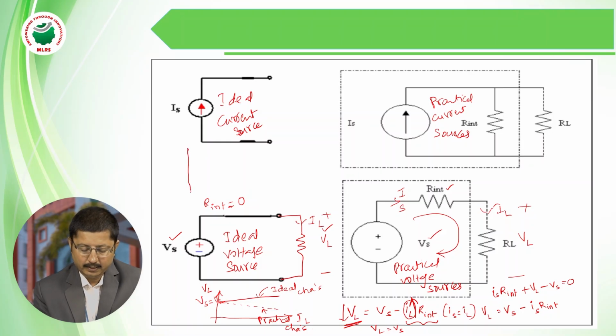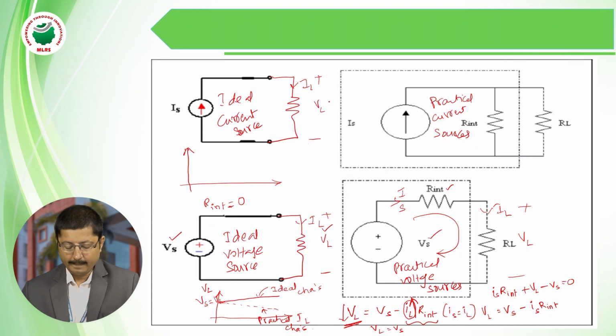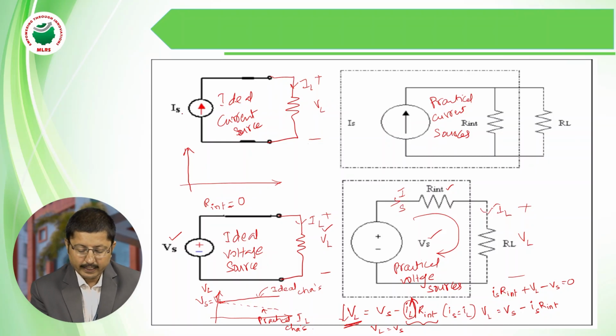So here, if we connect a resistance across these terminals, we can see the characteristics of these terminals, that is VL and IL. Whatever the source current is, the same current flows into the load, irrespective of the load voltage or terminal voltage. That means the load current is constant irrespective of my terminal voltage. So IL is equal to IS.